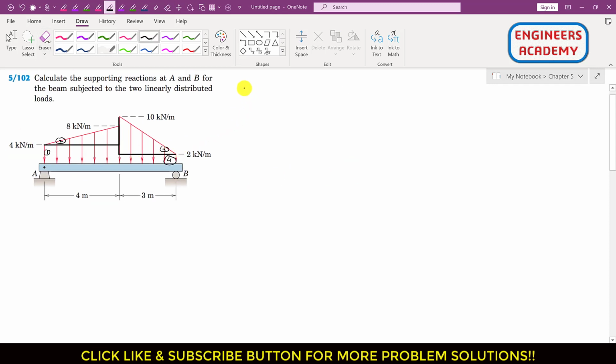Now we will use that equation. Let me write that equation here again, right? So x bar will be equal to x1 R1 plus x2 R2 plus x3 R3 plus x4 R4 divided by R1 plus R2 plus R3 plus R4, right? So now what we will do is find this x1, x2, x3 and x4, and these are the distances of R1, the resultant of area 1, the resultant of area 2, the resultant of area 3 and the resultant of area 4 from that point A respectively, right?